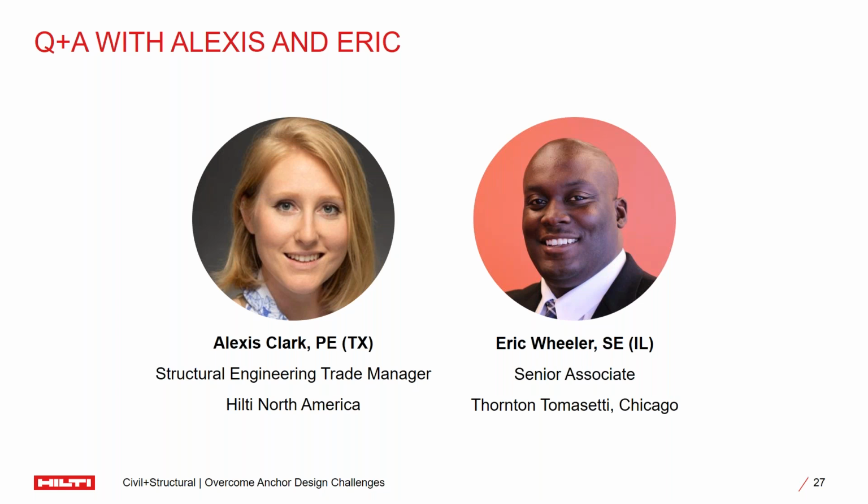Okay, and another question coming in is, can you have more than one width of brick in the design? Great question. That is absolutely something you can do. We do have valid technical information in 2 width and 3 width brick. So again, we only have that technical data for a certain number and different type of anchors. So when you go into the software and select either single width or multi-width brick, it will only show you the anchors that are valid because they have testing and published data for that specific base material.